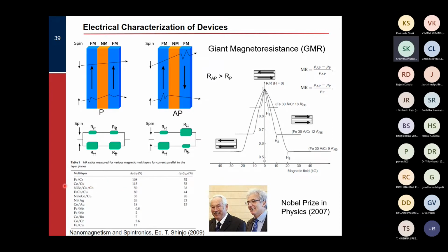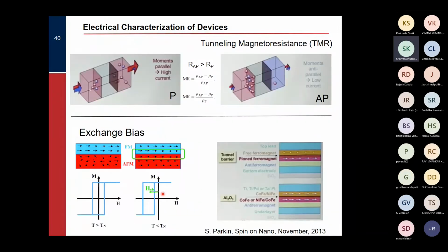And then for different cases, these numbers could vary between like 10 to 100, something like that. Okay, so now basically this particular kind of magnetoresistance structure can also be created in a different way. Earlier we used a metallic layer, that means copper or chromium, but I can simply use a non-magnetic layer to separate the two ferromagnetic layers.